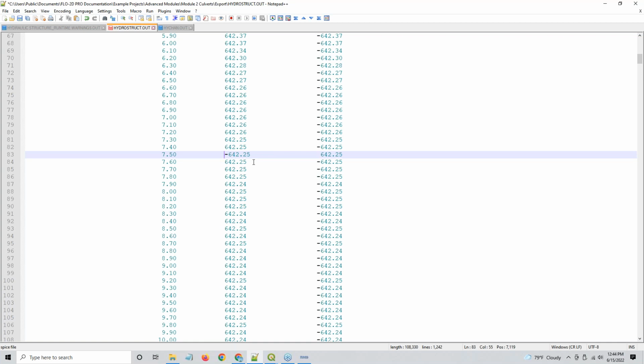If you start seeing things like this, negative to positive, you could have a tide condition, or you could have something wrong with your control at the outlet. So if this is going negative, positive, it could be because of a tide.